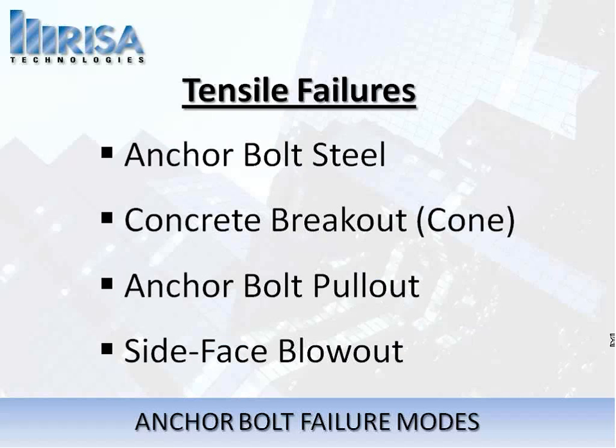So let's talk about the different failure modes that you can get with anchors. Well, the first is going to be anchor bolt steel, and this is actually a controversial topic because AISC generally would govern steel strength, but ACI actually references it here. In order to avoid any sort of problems in terms of our program implementation, we're going to check your anchor bolts for both the AISC requirements and the ACI requirements and report them both back to you. We leave it up to you as to which one you consider governs, although for my own designs, I prefer to just meet both requirements.